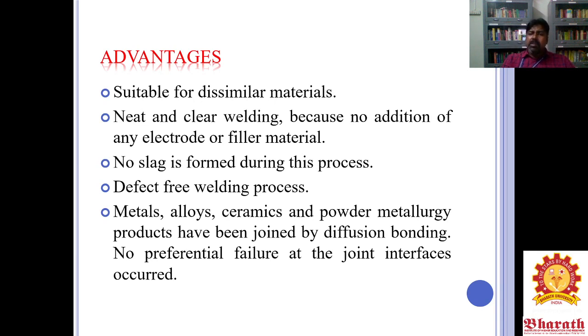Because there is no addition of filler materials or electrodes, right? And no slag is formed during this process, so there is no removal of slag, and we are reducing the time. Then we get defect free welding. Metals, alloys, ceramics, and powder metallurgy products have been joined by diffusion bonding. So there are no preferential failures at the joint interface.